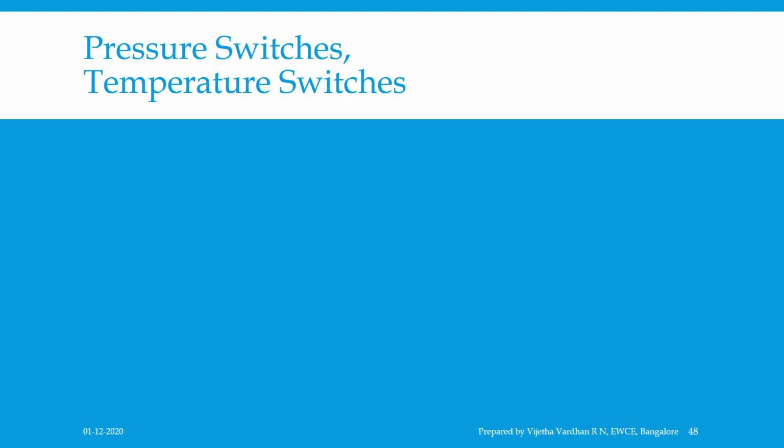A normally open switching element is one in which the current can flow through the switching element only when it is actuated. The plunger pin is held down by a snap action leaf spring, and force must be applied to the plunger pin to close the circuit. This is done by an electrical coil which generates an electromagnetic field when current flows through it. In a normally closed switch, current flows through the switching element until the element is actuated, at which point it opens and breaks the current flow.